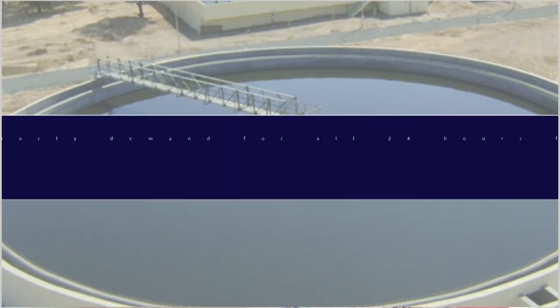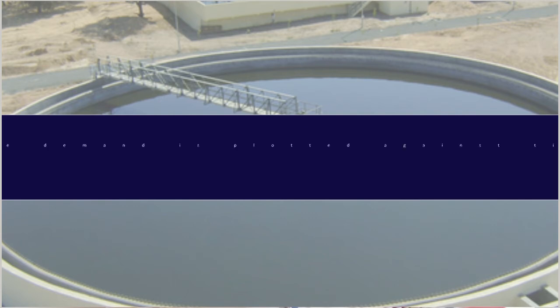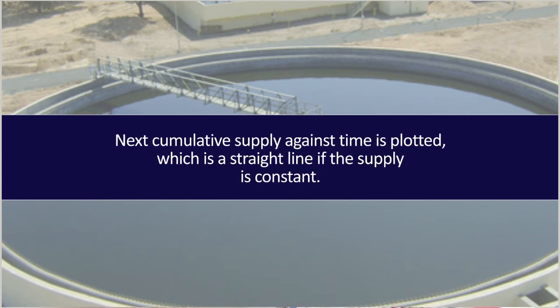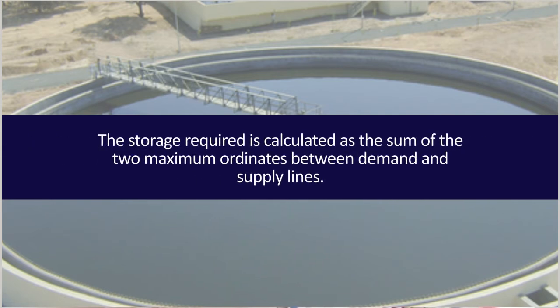First, the hourly demand for all 24 hours from the day of maximum requirement is determined. Cumulative demand is plotted against time, which is known as the mass curve of the demand. Next, cumulative supply against time is plotted, which is a straight line if the supply is constant. The storage required is calculated as the sum of the two maximum ordinates between demand and supply lines.